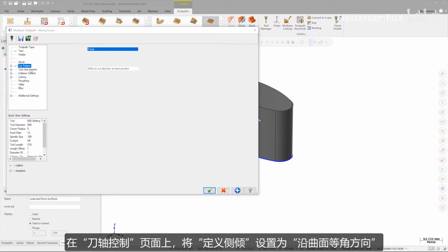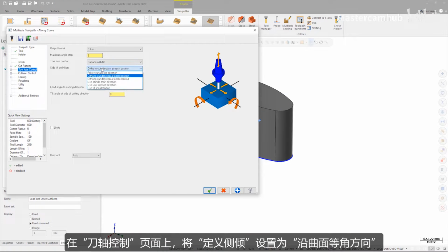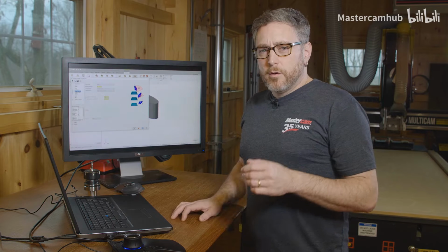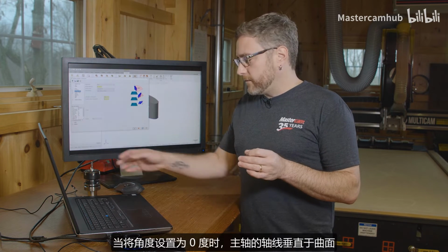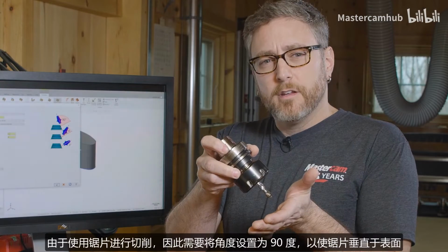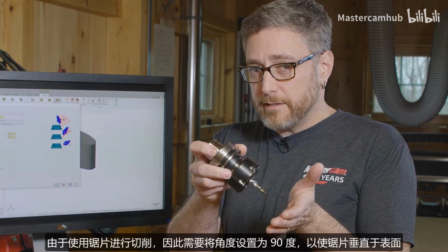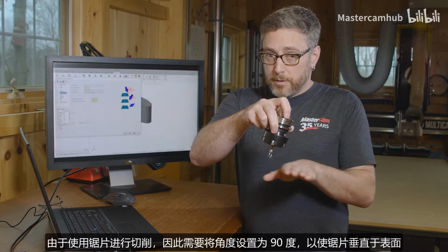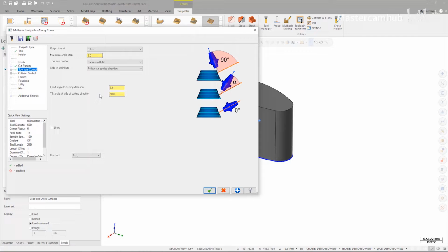On the tool axis control page, we need to set the side tilt definition to follow surface ISO direction. We'll also need to change the tilt angle at side of cutting direction as well. When the angle is set to 0 degrees, the axis of the spindle is normal to the surface. Since we're cutting with a saw, we need to set the angle to 90 degrees, so that way the saw itself is perpendicular to the surface.